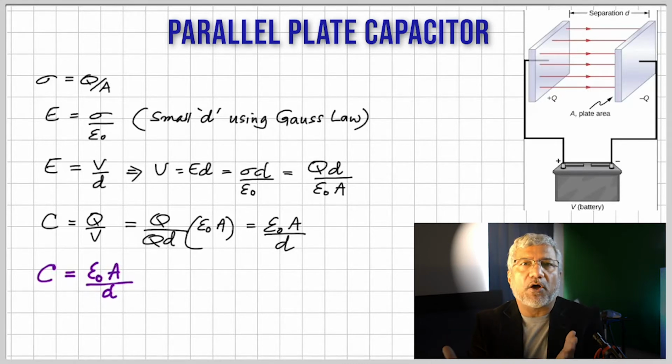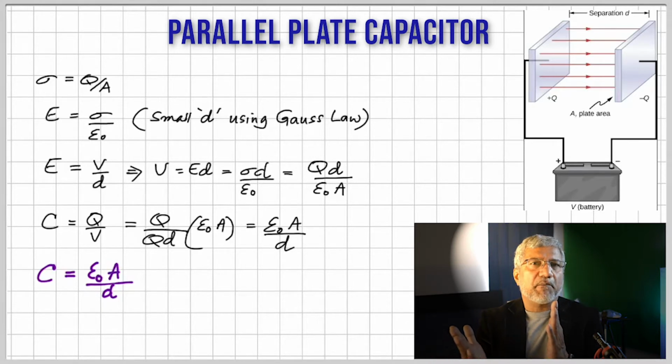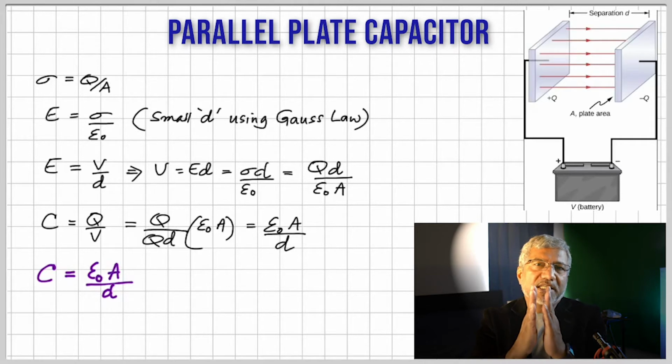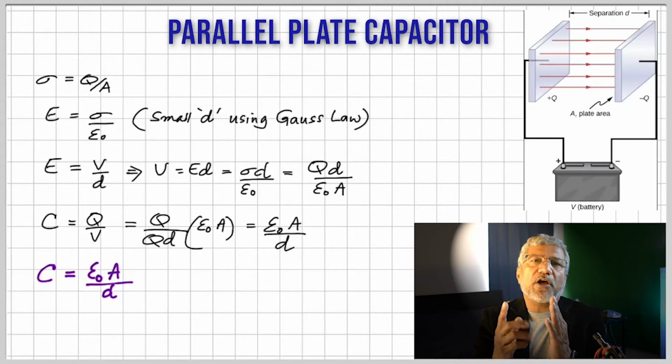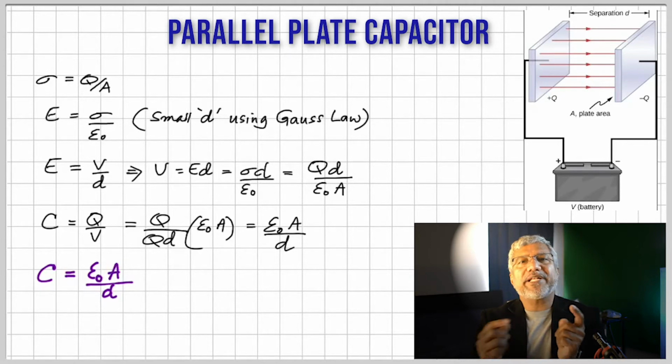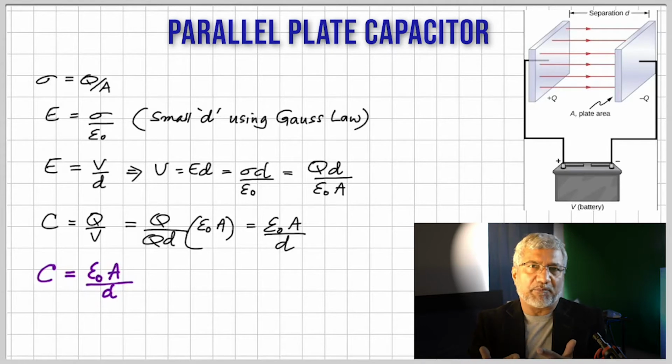Remember, air is already an insulator, but its insulation properties are not that high. But instead, if we could insert a piece of mica, you see that it insulates more. So now, not only are you avoiding the discharge between the plates, you are also increasing the capacitance.